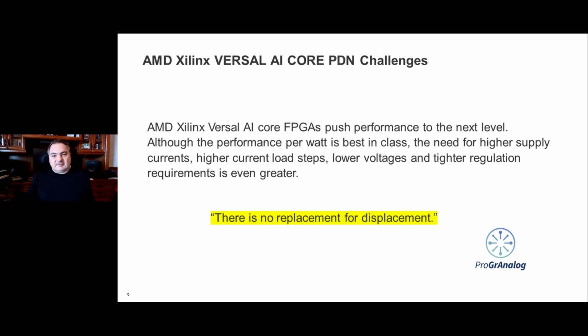You can't rely on simulations. I mean, they can help a lot, right? But at the end of the day, you can't release a product into the real world in any kind of volume environment without actually having tested the PDN. Now, you can potentially test it with the target device, but you can never go beyond what the target device can power. And if you're looking to design some margin into your power supply, then you need to test.